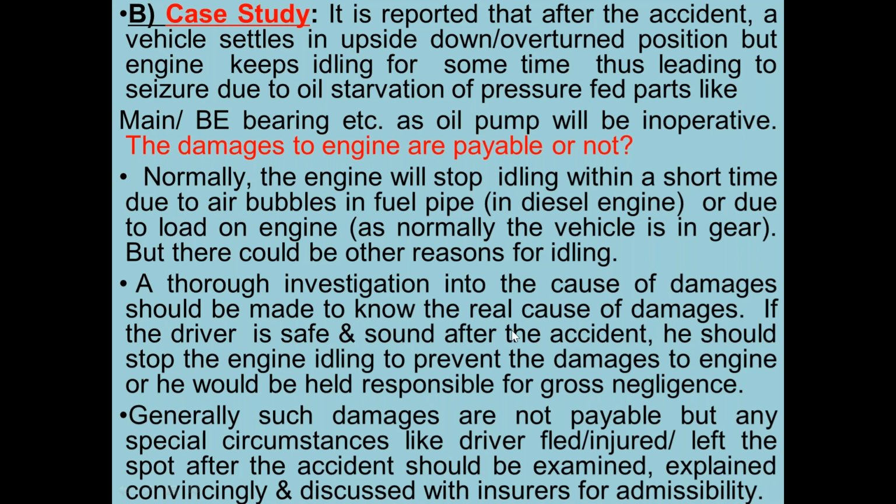Normally, the engine will stop idling within a short time due to air bubbles in fuel pipes, especially in diesel engine, or due to load on engine, as normally the vehicle is in gear. But there could be other reasons for idling. A thorough investigation into the cause of damages should be made to know the real cause of damages.